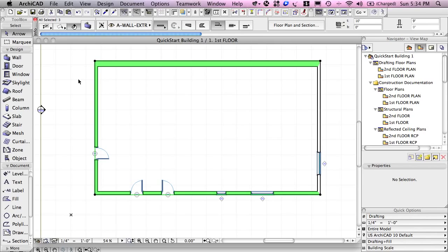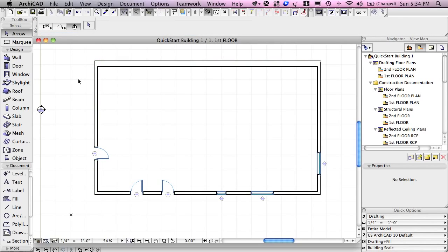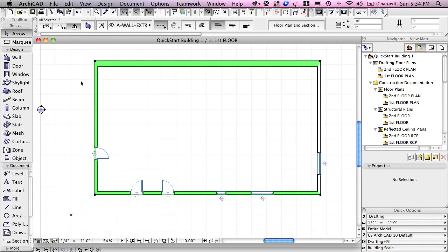So I'll click an empty space to deselect, and now when I want to select here, if I click 2 points, this determines a rectangle, and then I can select things there. In this case, it doesn't make much sense, but sometimes a building has parts of the design on an angle, and this can make it easier to select those elements on a similar angle here.